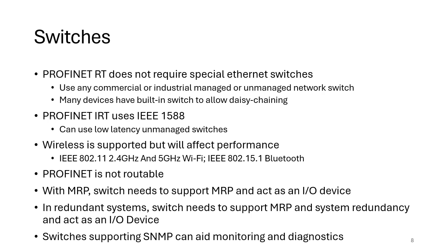You might also consider using STP, spanning tree protocol, or RSTP, which is rapid spanning tree protocol. Just be careful, but if you're using a PROFINET network for I/O purposes, STP is probably far too slow because it has a recovery time of seconds. With RSTP, you're still looking at several milliseconds, so I would say even RSTP wouldn't be fast enough. So if you're worried about a failure on the device, then you need to arrange it to use MRP.